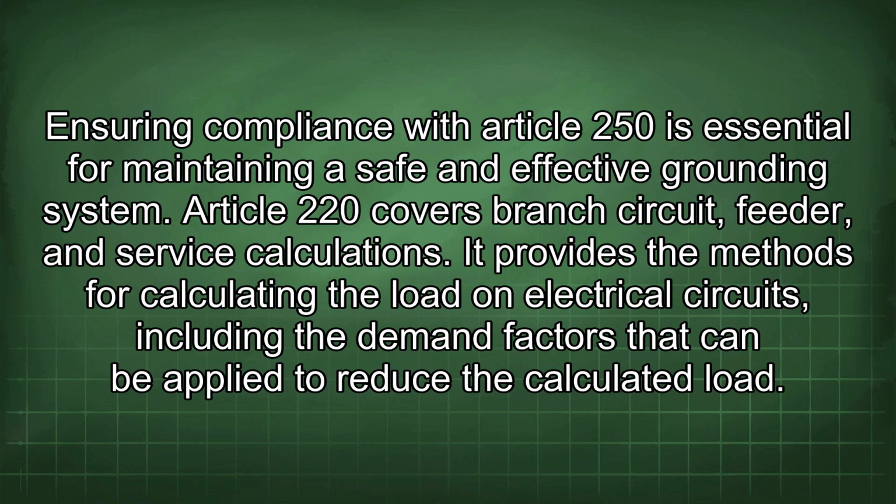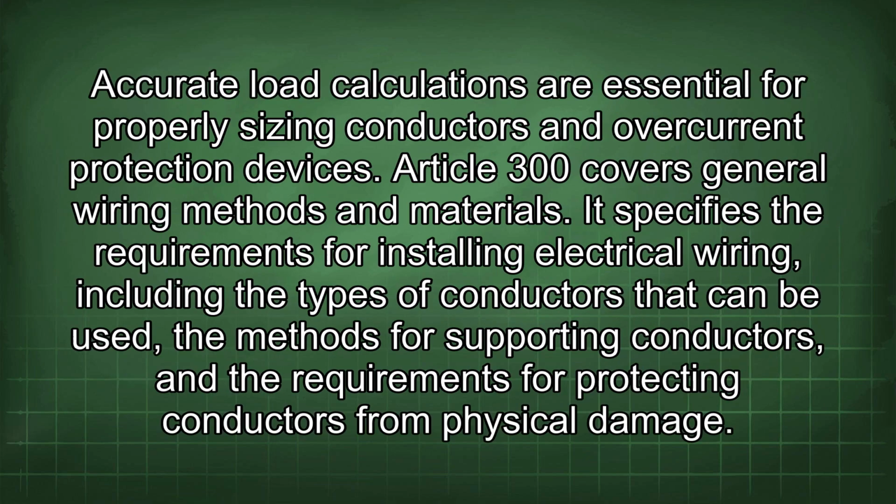Article 220 covers branch circuit, feeder, and service calculations. It provides the methods for calculating the load on electrical circuits, including the demand factors that can be applied to reduce the calculated load. Accurate load calculations are essential for properly sizing conductors and overcurrent protection devices.